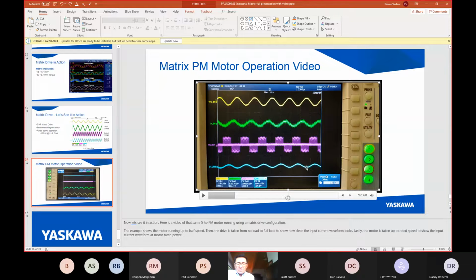So applications that require a sinusoidal output to the motor are advantage matrix drive, because you have to add even more cost to the conventional drive. A sine wave filter on the output of a conventional drive, whether you buy from TCI, MTE, or any of their competitors, will just about double the cost of the VFD as well.